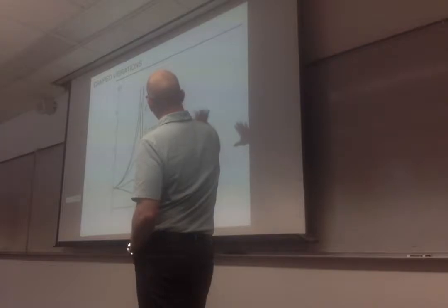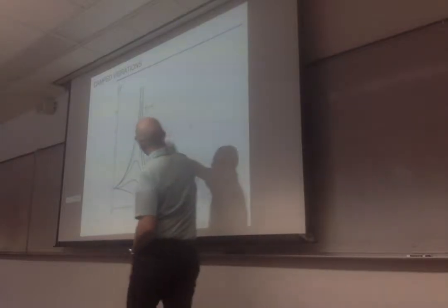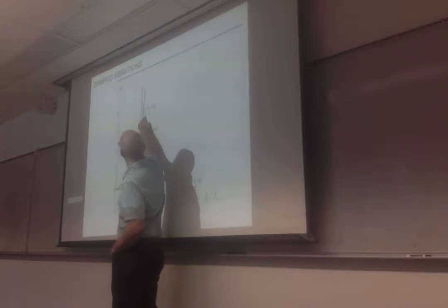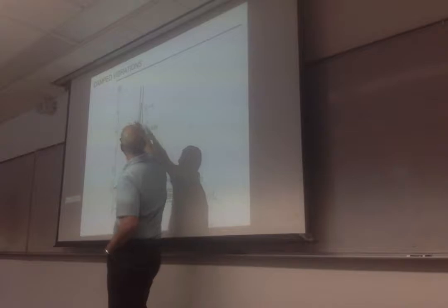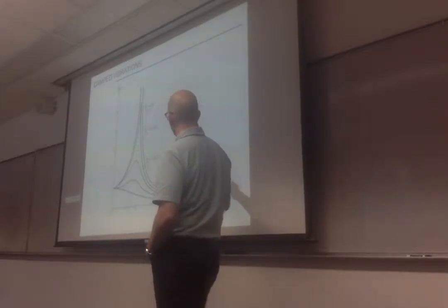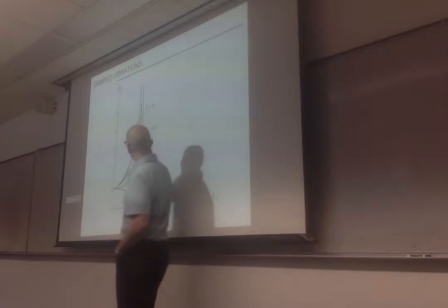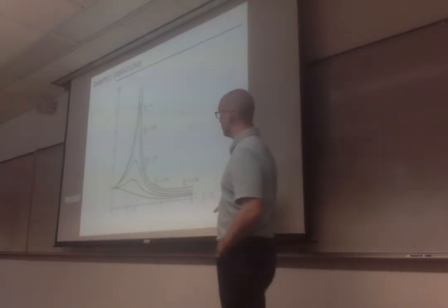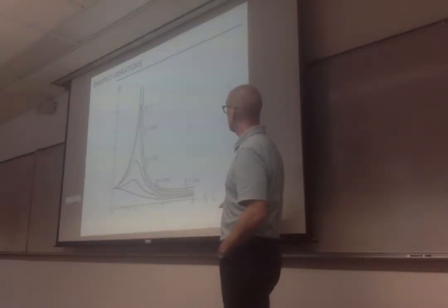So what you will have here is the case where we're dealing with no damping, so that goes to infinity. But in every other case, where you have a certain level of damping, you still have a bump very close to the ratio where the forced and natural frequency is equal to 1.